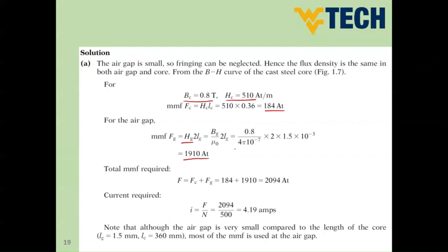Why? Because again, the air gap flux resistance, which is reluctance, is going to be much higher compared to the magnetic material. We mentioned before, guys, mu r for magnetic materials we use in most of our applications could be from 2000 to 6000. So this means the reluctance of the air gap could be 2000 to 6000 times that of the magnetic material.